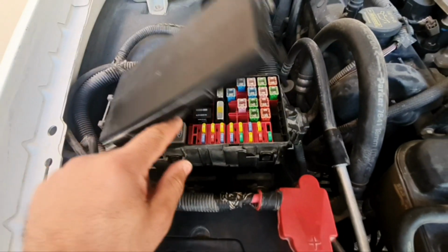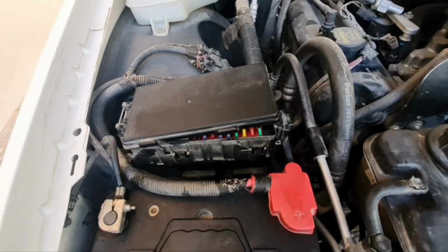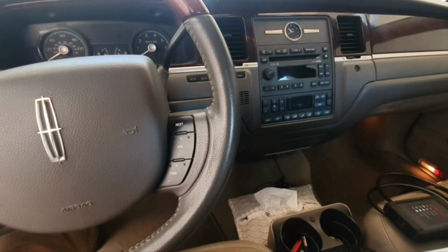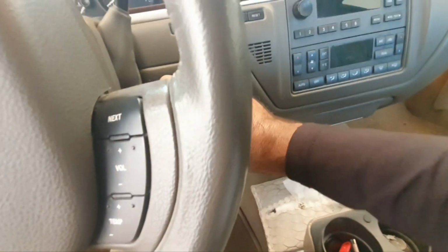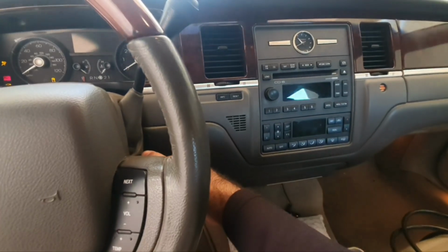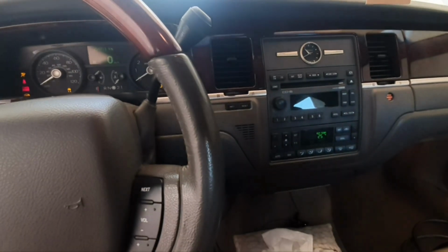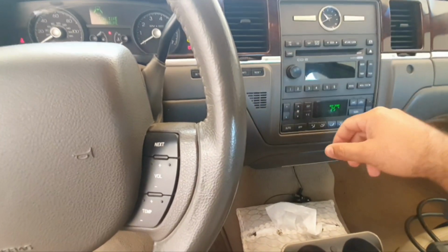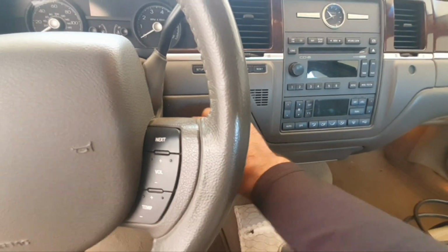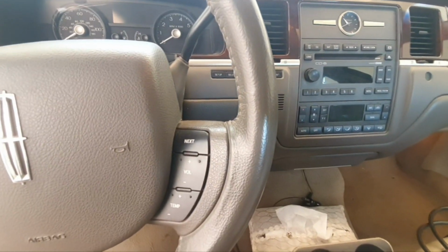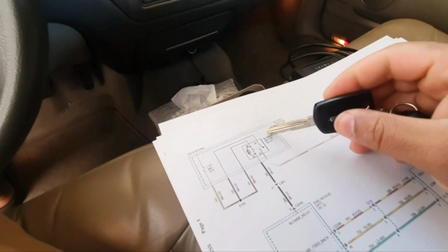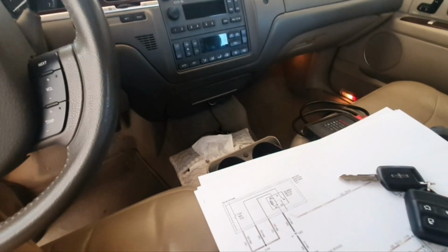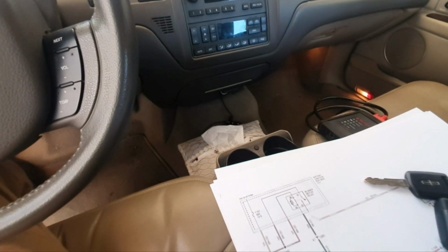Let's go and check again, when we switch the ignition on, whether the blower fan will start or not. As you can see, I turned on the ignition key and the fan is not blowing anymore. So now I will go and put a piece of wire, as I said, at this position, and see with the key off if the blower motor starts to blow or not.